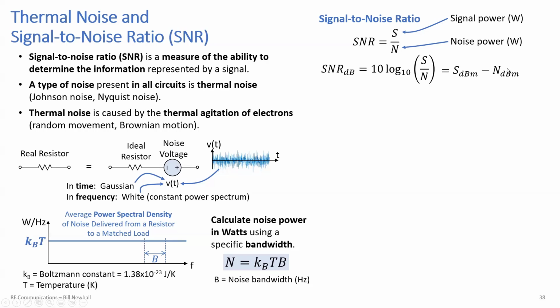Now, I want to give you an idea of what this looks like. How do you visualize what a good SNR and what a bad SNR is? As far as performance, different receiver techniques deal with signals differently. Some receivers can receive really low SNR signals and do just fine, giving you the information back, using error correction coding, integration and despreading, and we won't get into that. Some receivers aren't so good, like your FM radio in your car. You drive behind a truck or you move forward at a traffic light, you get into a fade, and all of a sudden your music gets all staticky.